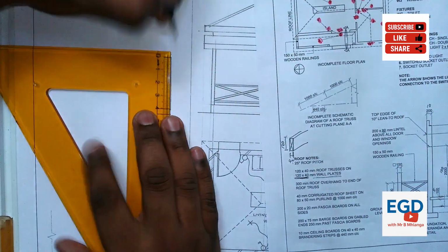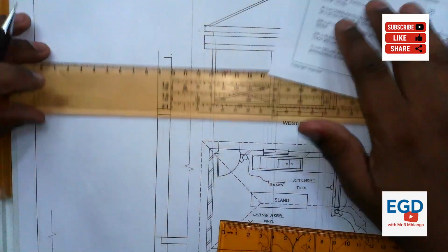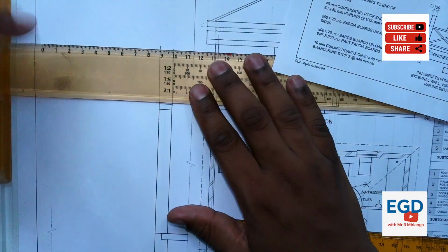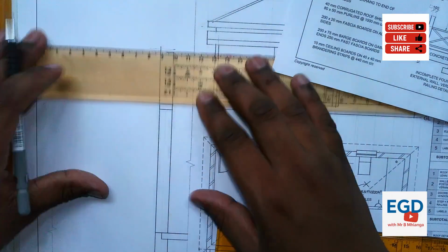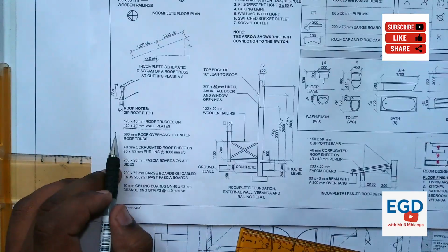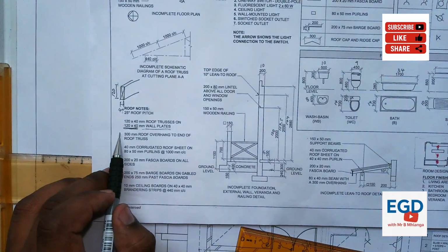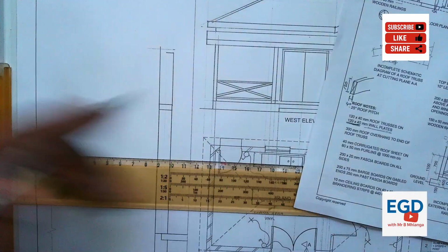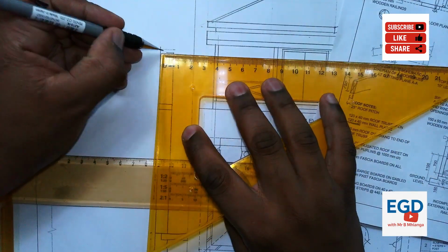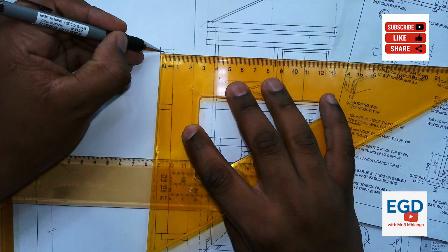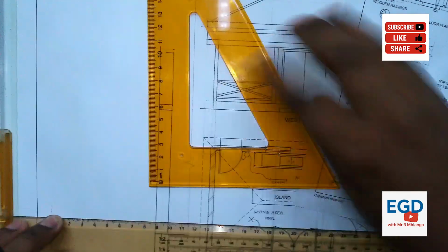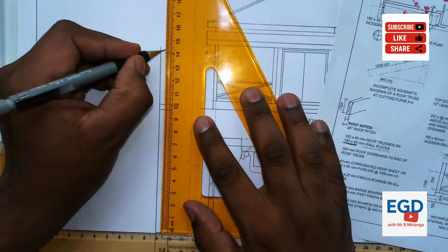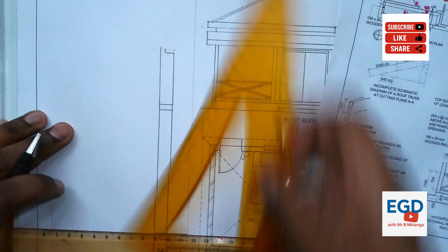I'll mark there. Okay, then I'll just draw a light construction line to my left. Okay, and then the width is 120, so I'll just divide this by 20. So what's the answer? The answer is 6. So I'll measure 6 going in. 6 is somewhere there. Okay, and then I can just draw that rectangle.